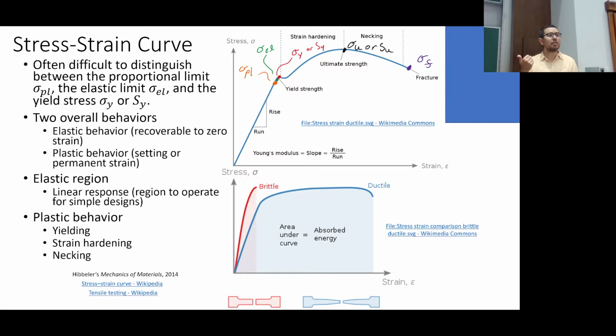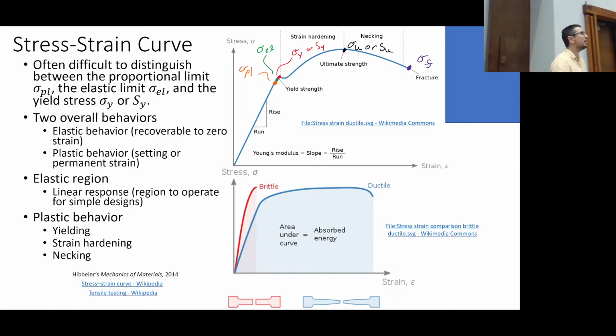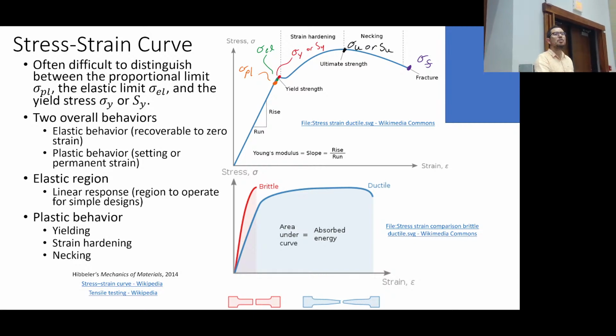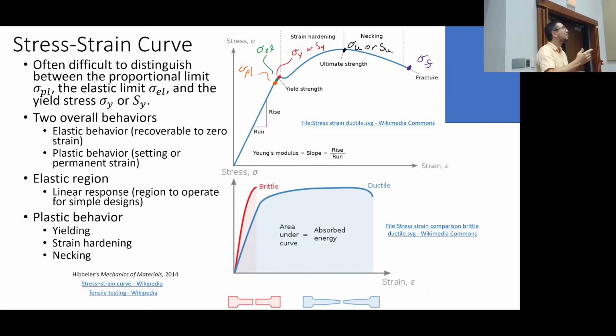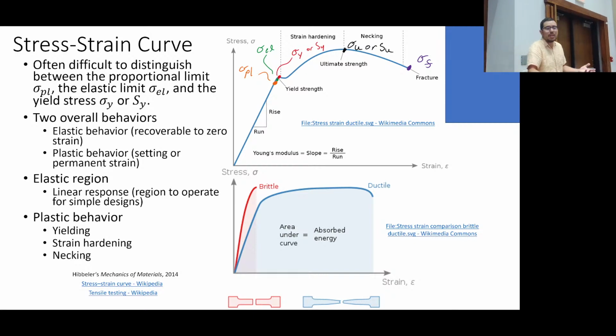And it's just rise over run. So you tell me, if you were given this chart, what are your options for calculating the elastic modulus? No equations besides rise over run. What are your options? How would you do it? Yes? Just calculate it that way. Okay, and what would be some candidates for your two points?